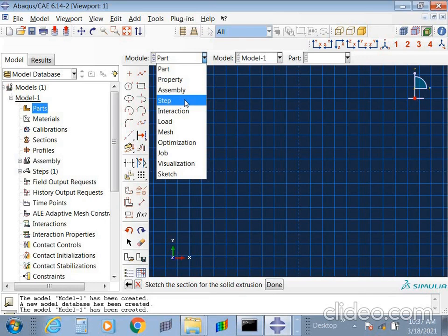And one more speciality of Abaqus is it follows naming of that particular component. Whatever name you give, it will take that name as an ID. The other softwares, for example your Workbench, ANSYS APDL, or Nastran, they all follow ID values. That means they know number systems, but your Abaqus knows a naming system. Okay, so I'll show that once it is done, how it will be in your deck. We call your coding, whatever code we write, a deck here.